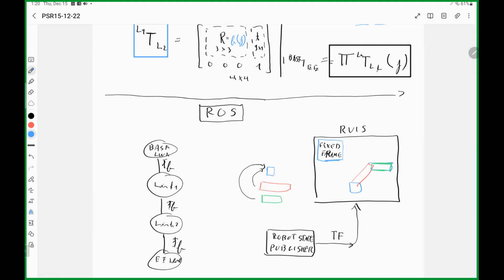Similarly, it derives the DH, the Denavit-Hartenberg parameters, from the URDF. All right. So from the URDF, you will feed it. Well, let me first do all the steps. So you have your URDF file, and you will load a ROS param called robot description.